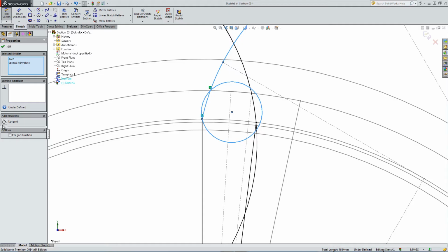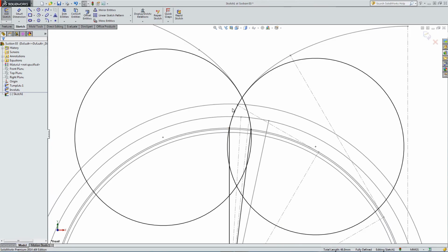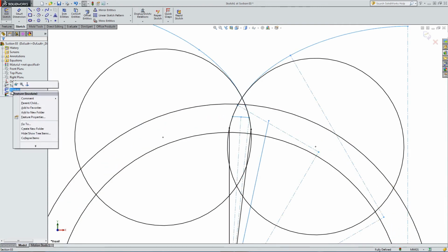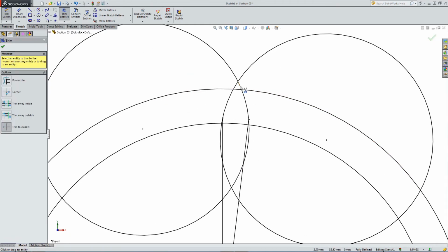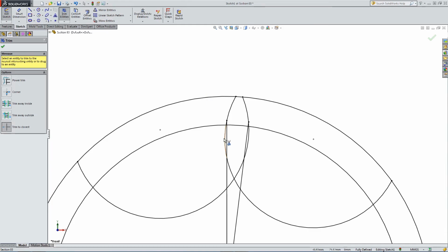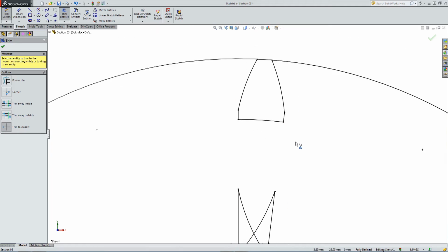So I'm just mating the geometry I want. You might say forming the curves kind of invalidates the involute, but it's good for the CAD representation, and you'll see at the end that SolidWorks will actually animate the gears. So let's just get rid of the geometry we don't want. We're just trimming it away.